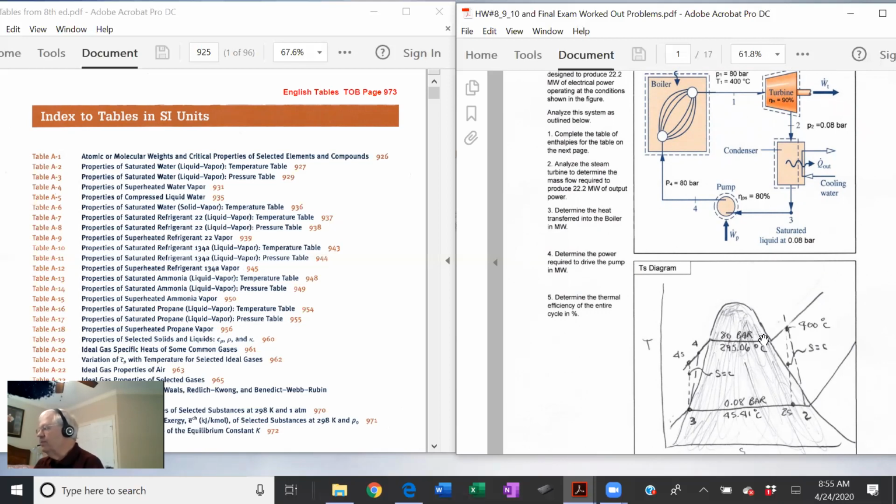Now, by the way, the temperature through here is 295.06 degrees. You can look that right off the saturated table. So the pressure and temperature are dependent through the dome. Then when we go out here, the temperature increases. So we're at 400 degrees.